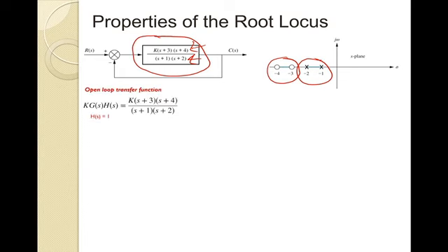And as we look at that open loop transfer function, we could put it in that form, for example, kgh. Because we have a unity feedback system here, we'll just say h is 1. And so we'll have the gain k, and then all of the other things, as we've already mapped on the S-plane, represent g of s, the open loop transfer function. Now, to get a closed loop transfer function, we've shown you this in previous modules. I'll leave that to you as an exercise. Hopefully, you should be very good at this by now, creating this closed loop transfer characteristic as shown here.